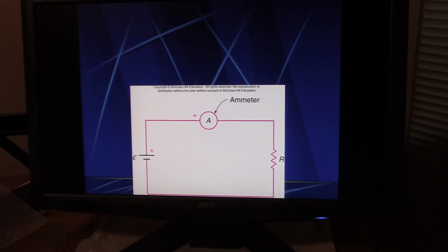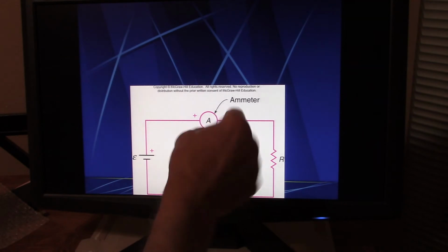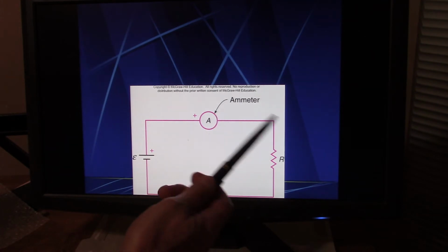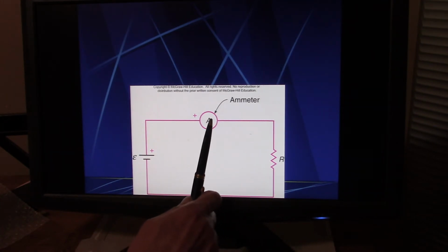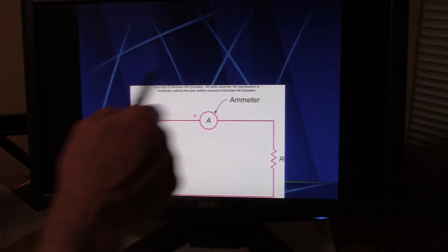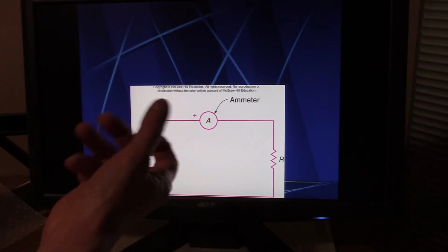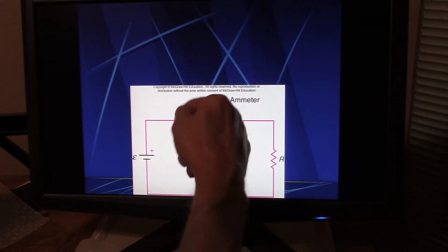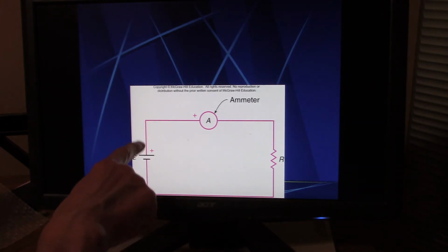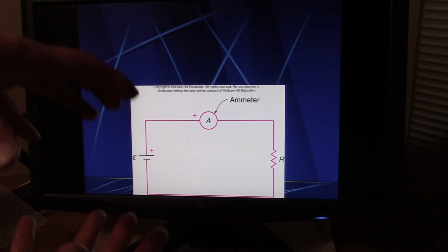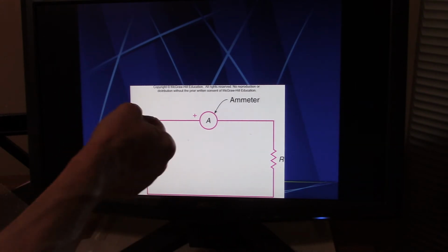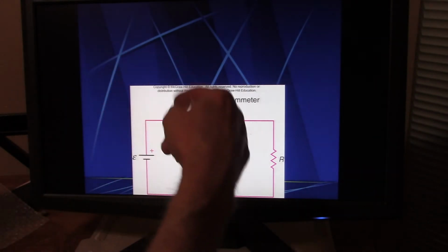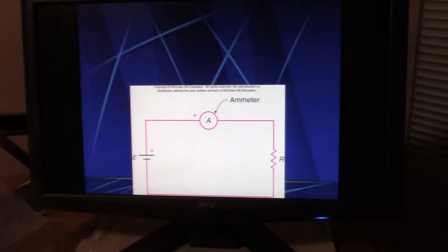Now a lot of you folks in automotive, there's actually a clamp-on. Although there are two kinds of ammeters. One, you would have it right in the circuit and it would permanently be there and always measure your current. But if you're just checking current, typically there's a device that doesn't actually break the circuit. It goes around the wire. When electricity flows, there's a field, and you can measure the current without breaking the wire.